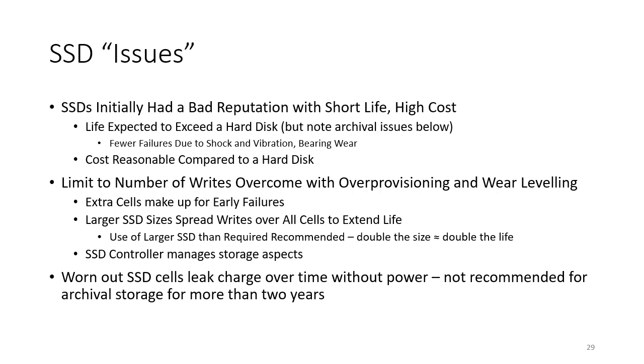So it's not a problem if the system's powered up continually, because the SSD and the controller will manage all of that and keep everything refreshed, and you won't lose anything. But if you are turning a device off for a long time and expecting to keep its state, then you might find that it's actually lost its memory over a period of maybe more than 2 years. So that is still one issue with SSDs.